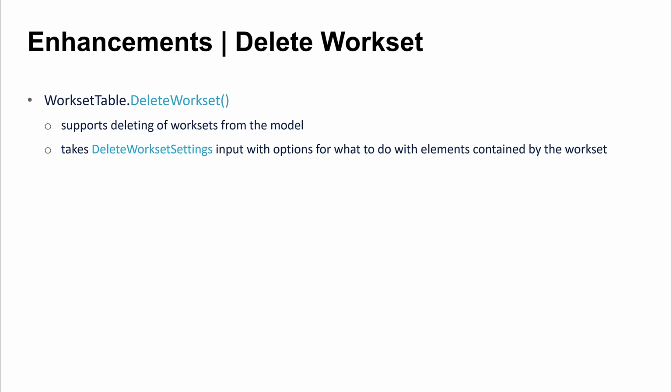Another area is enhancements to the worksharing API, and specifically the ability to delete a workset. This has been a long-time request, so I'm excited to add this. The method to delete a workset takes in a DeleteWorksetSettings class with a bunch of options that determine what to do with the elements in the workset.